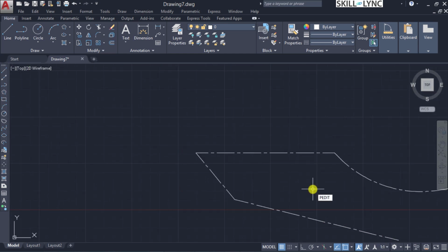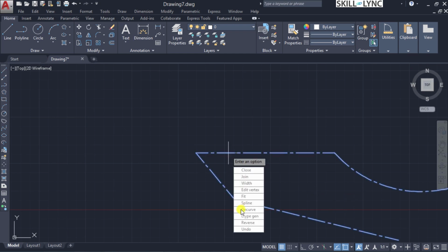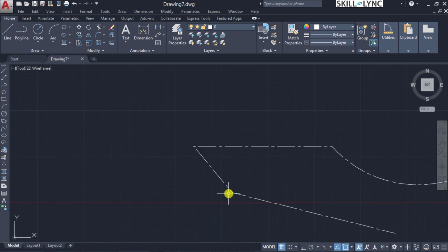When we change the option to the on state, now each vertex will have a smaller line segment there. At this join point, it's not a perfect longer line, but rather the pattern is running through the vertex as required. So this is the linetype generation command.